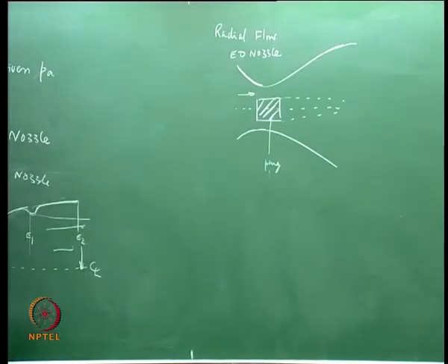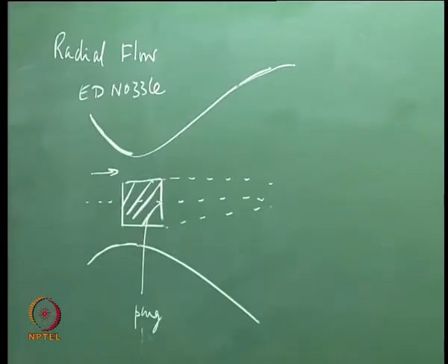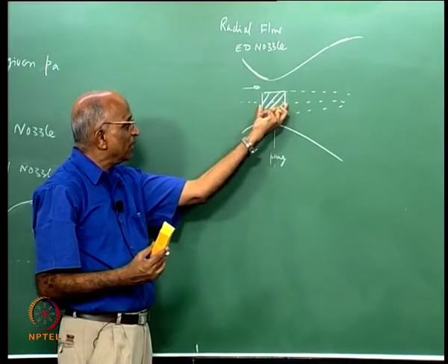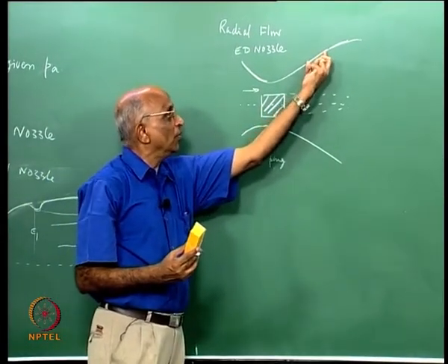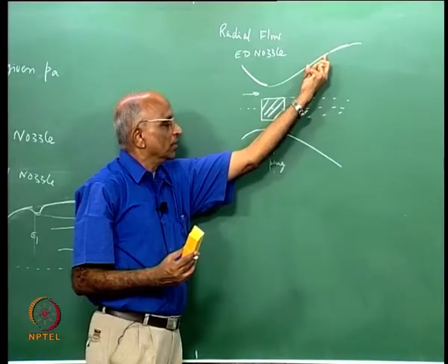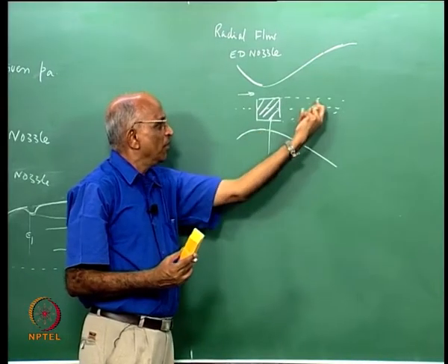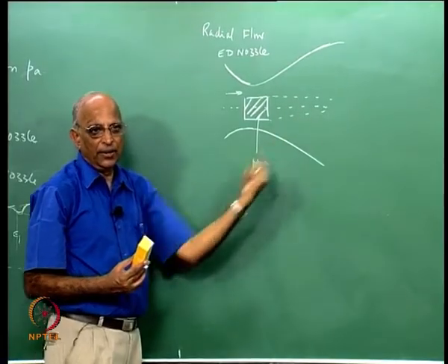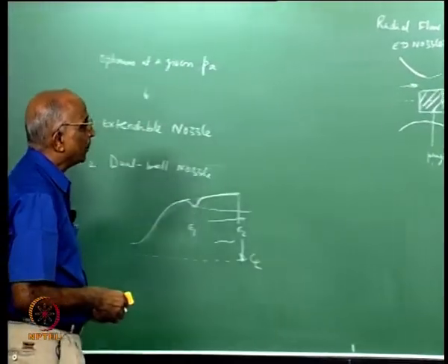See, what we have to do is we want the nozzle to operate at different altitudes. Therefore, what we have done is we have done with a plug, we allow the contour to change the pressure of the outer flow, but the inner flow we keep free such that the inner flow can expand. This is the expansion deflection nozzle.